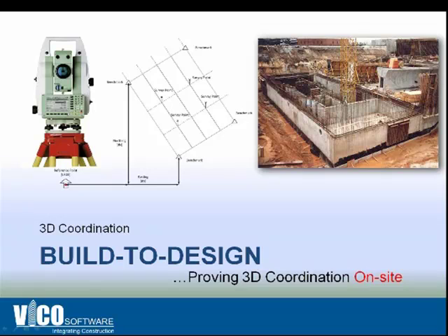Those of you who are Trimble customers may be familiar with their robotic total stations and some of their other field automation equipment. And really what you can do at this point, since you have a model that's highly accurate, is to use points from the model like these constructability markers, or to use the center line of ductwork, or to use the edges of slabs, and mark those spots and then transfer that information as a layout with X, Y, and Z based on your site survey, and put a station in the field that can then verify that installation is going according to plan.